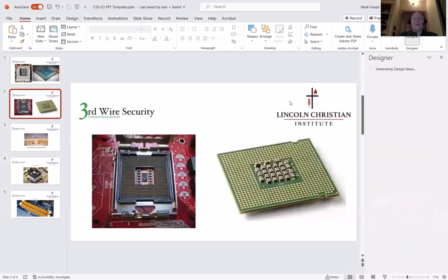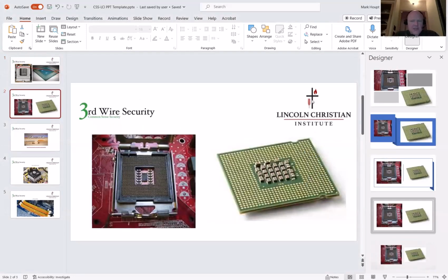On the second page that we're looking at here is an example of the LGA format. And you can see on the right hand side that although there's a similar scenario where there's a green circuit board and the chips for the CPU are in the center, the pins are replaced with more of a flat surface for our contact points. And then on the left hand side, you can see the socket that it goes into, and you can see that the raised pins, although much smaller than the PGA version, are available there for receipt.